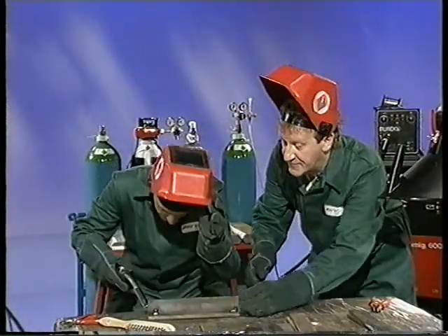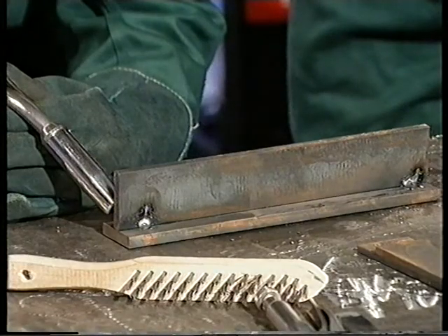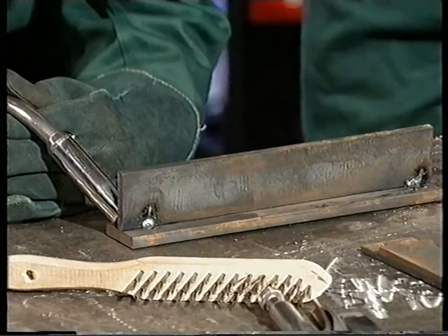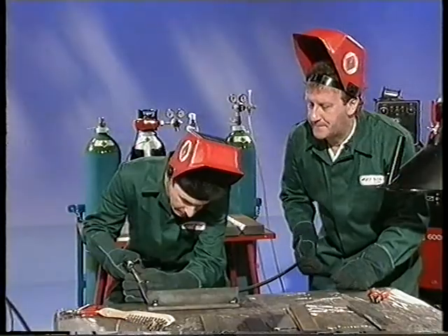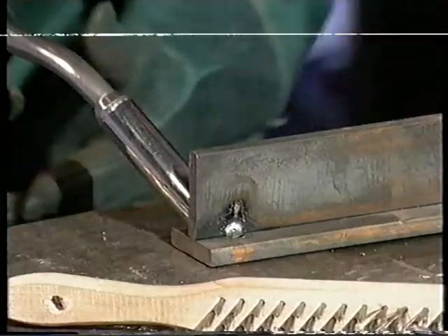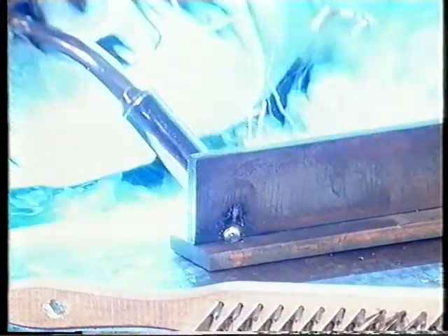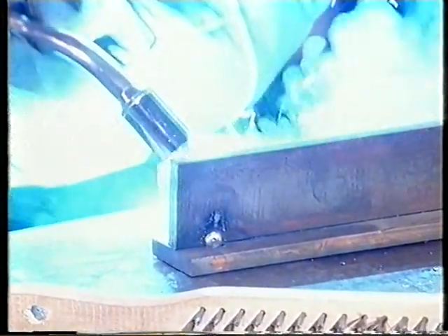That's right. If you can put that torch at around 45 degrees, between on the 90-degree angle, get the wire right into the root of the weld and attempt to hold about an 18mm stick out. Okay. Try that then. Mind your eyes. Okay, that's not bad. You can afford to slow down a little and let the weld spread across both plates. That's pretty good.